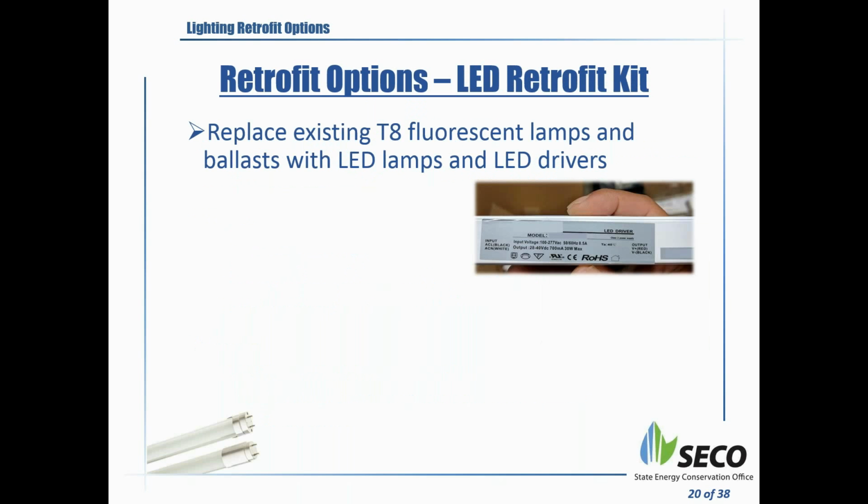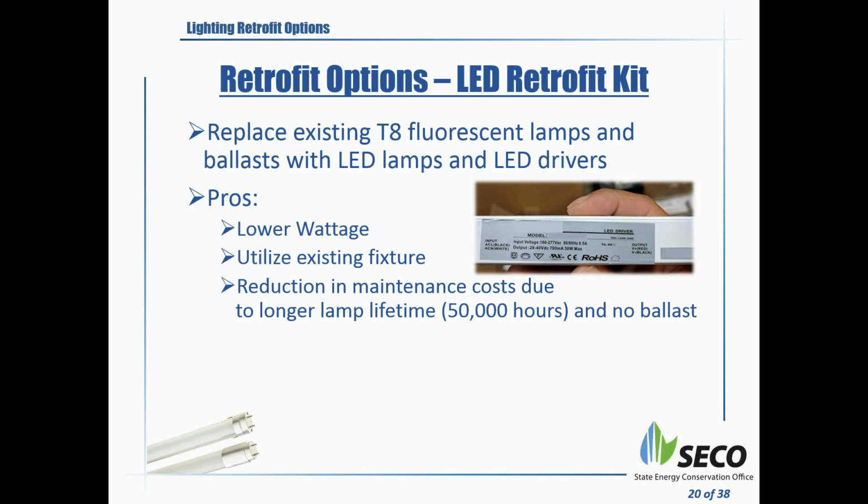So the retrofit option, LED retrofit kit. This is where you say, I want to get rid of the ballast. In that case, you'll have to have the driver installed over there. So it's replacing existing T8 fluorescent lamps and ballast with LED lamps and LED drivers. The advantage of this one is lower wattage and it utilizes existing fixtures. It's in the same fixtures you do the retrofit. Reduction in maintenance costs due to longer lamp life.